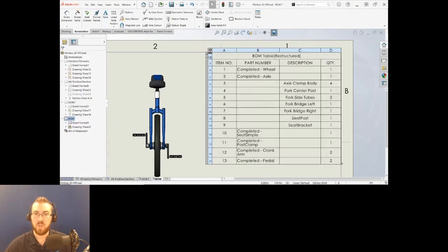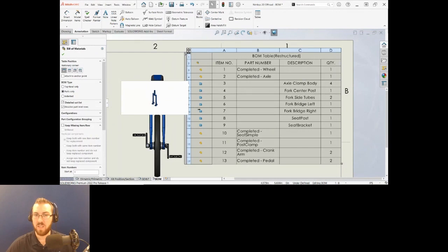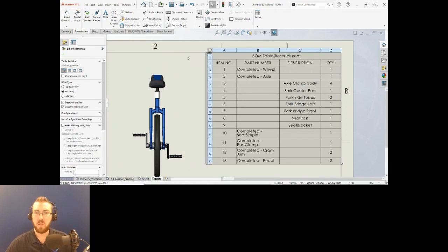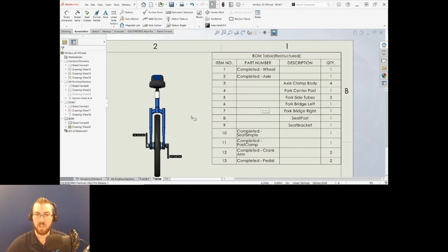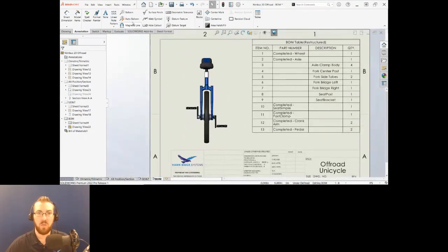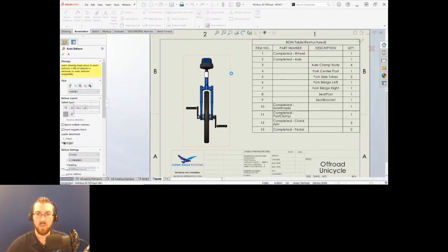If you prefer to use that, you can use a little flyout here. Each of these is a body of a multi-body part, and you can see that description property. Again, that's why I filled all those out. This was simply not possible before. You would have to use indented in order to get this information. And of course, that's going to enable us to auto balloon this view.